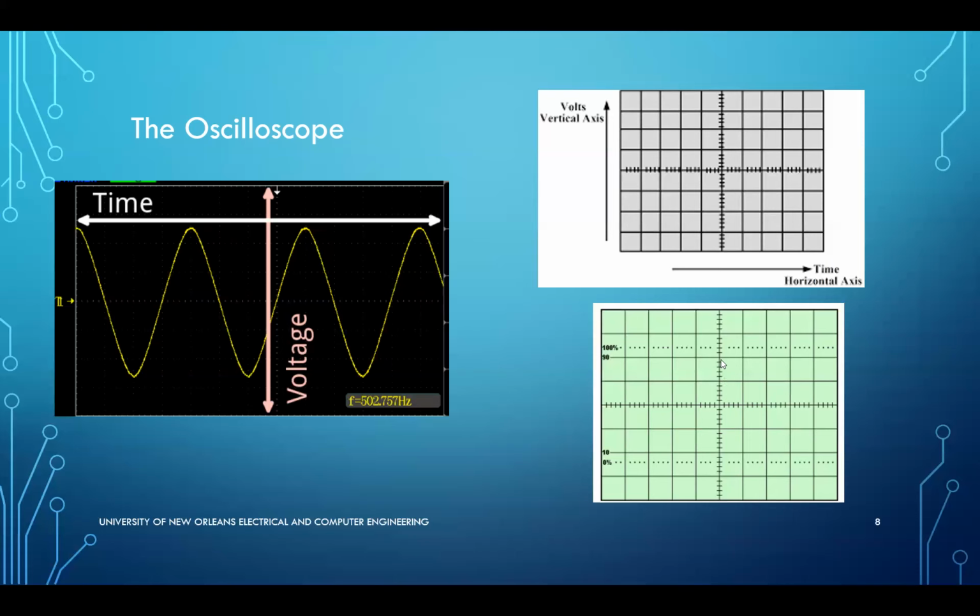Again, if I set up the scope to be 1 volt per division, then each of those little ticks will be 1/5 of a volt, and so forth. Same thing goes for the time information. So that gives you a little more detail on what you can see.